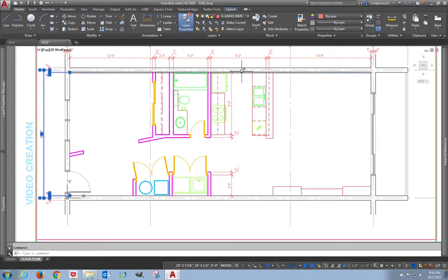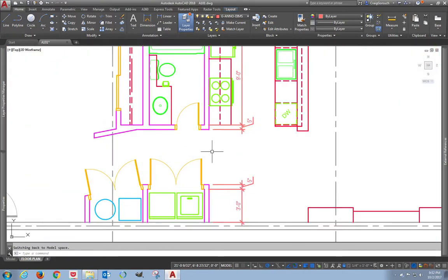Just like when I was creating this bathroom, I offset the wall 9 feet, and then I offset this bottom one 3 feet. In construction, they're going to do the same thing. They're going to start with one wall, and they'd offset it 3 feet, and they'd basically draw a line in chalk right there. And then they would do the same thing for this side. Alternately, we can go ahead and put a dimension going all the way across. It really doesn't hurt anything.